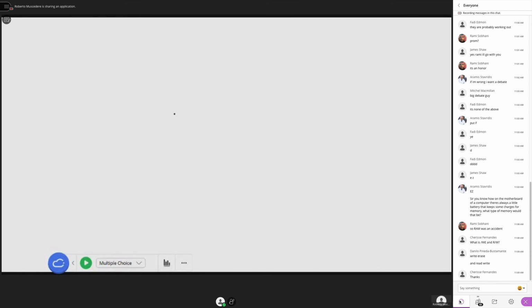So a typical memory cell would look something like this. Here's my inverter. Here's my other inverter. Well, that's not what inverters look like. Not really thinking much while I'm drawing this, am I? There's my other inverter, and it looks like this. So if this is a 1, this will be a 0, right? And if this is a 0, this will be a 1. So it's in harmony. Nothing is changing. The circuit's not switching. It's never switching. It's constantly static, and therefore we call it static memory.